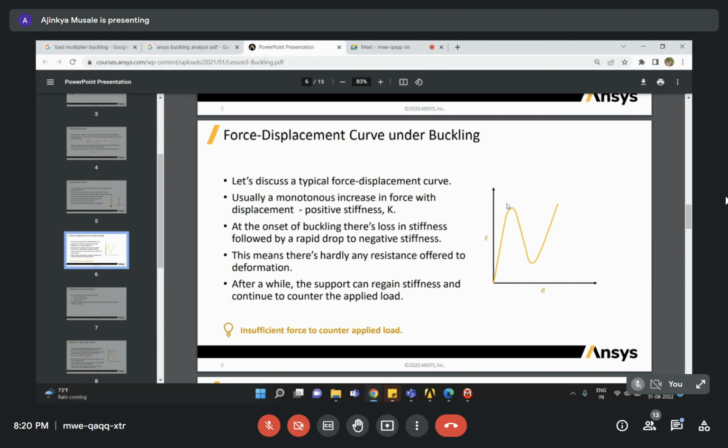Did you understand this? Maybe I can explain it again. In ductile materials, as I increase the load, my body deforms, afterwards it starts neck formation, and after that it just breaks. That's my general case. But here, as I'm increasing load, the basic difference is that my load is in the compressive direction.